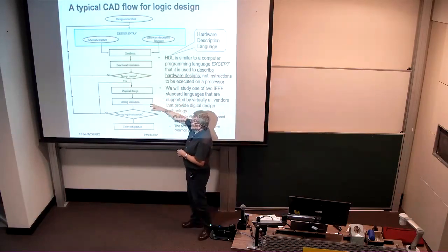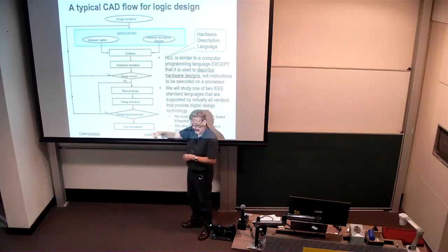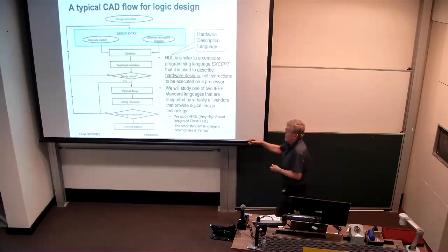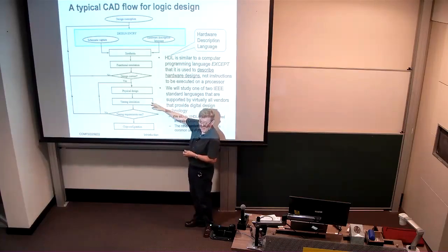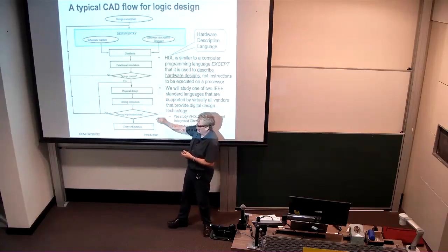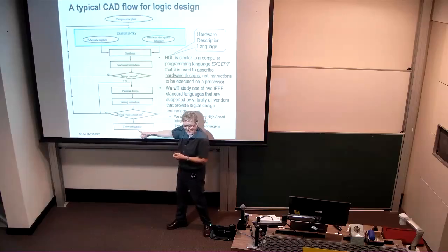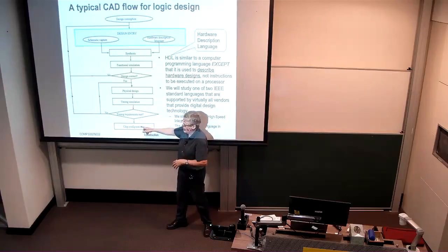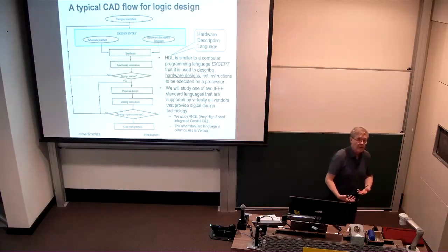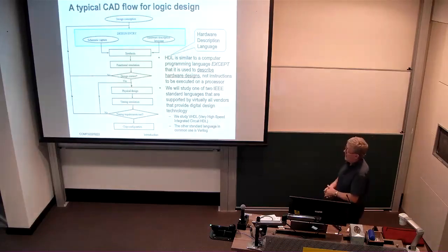When that's done, you can simulate how long it takes for signals to traverse the wires in the design. This is still a simulation. And confirm that it performs as desired. If it doesn't, you'll need to modify the design in some way. But if it does, then you can produce a configuration file, load that onto the device, and actually test it in situ, in silicon, on the FPGA, and check that everything's performing correctly.